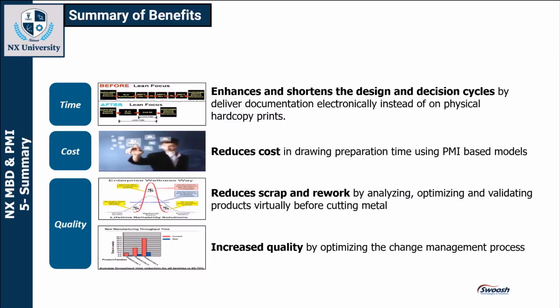Take a look at a summary of benefits with the model-based definition. So looking at model-based definition and applying that PMI to your physical models, this is going to allow you to save time. It's going to enhance and shorten the design and decision cycles here with your products. It's going to deliver documentation electronically instead of on that physical hard copy prints. You can share that with your vendors, your customers, share it down with the machine shop if you need to. You can still create those drawings, those physical drawings if you need to do that. And I did show that earlier in the presentation by inheriting the PMI into a drawing view. But now the physical model is going to be the source of truth here.